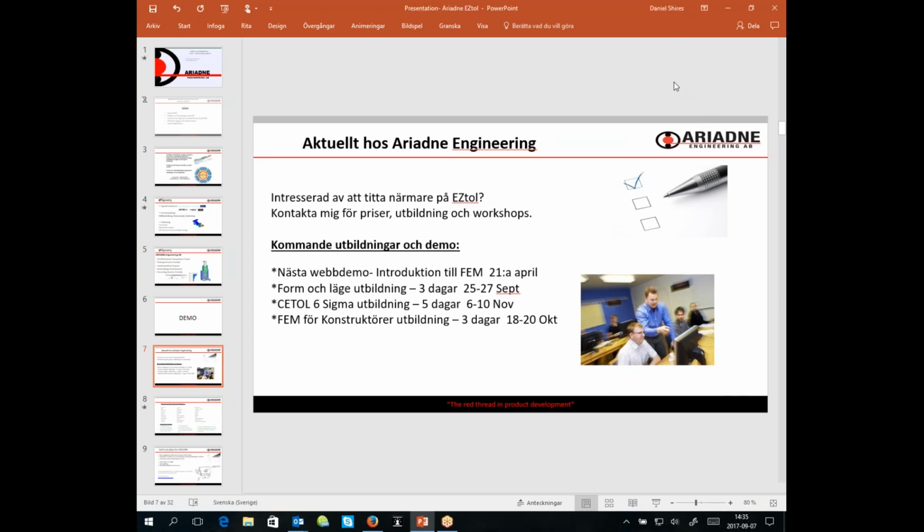Oh, here's another question. Do you see the questions too, Stephen? The 4 holes in the stack-up. I suspect that the reason you're asking is about fit of patterns. It's possible to evaluate the fit of holes in a pattern, but you won't need all 4 of those. You can actually do it with 2 of them, and if you're using the same tolerance on the entire pattern, then through consistency, the others will be there as well.